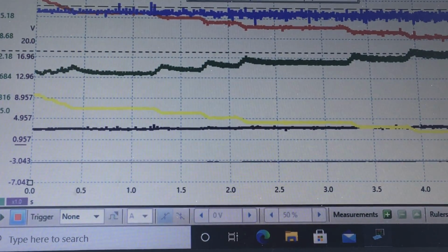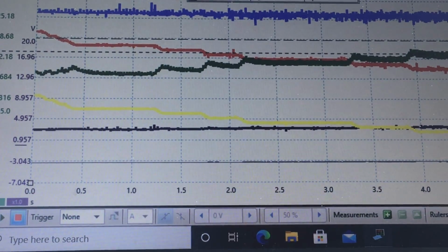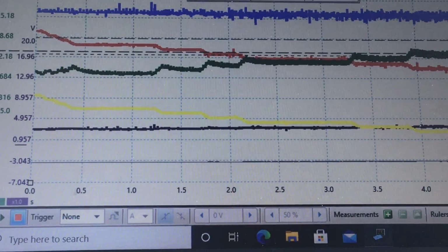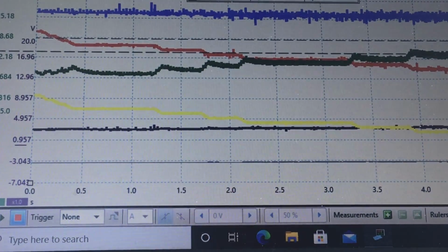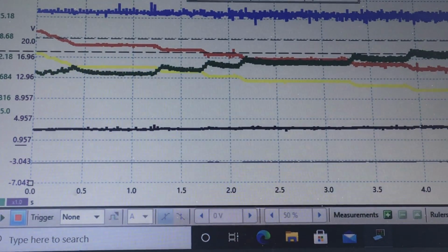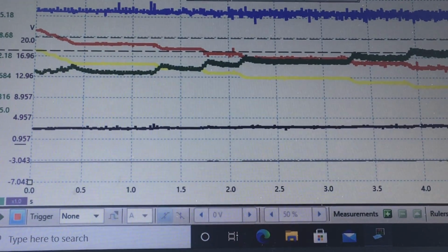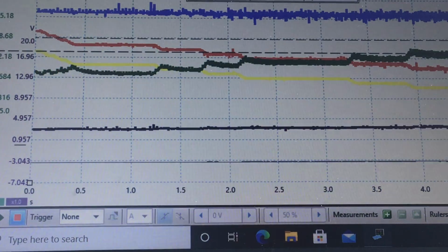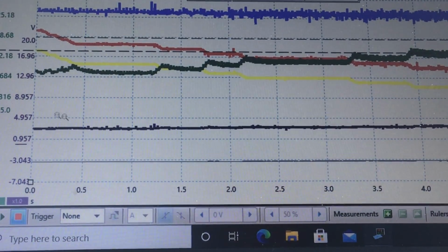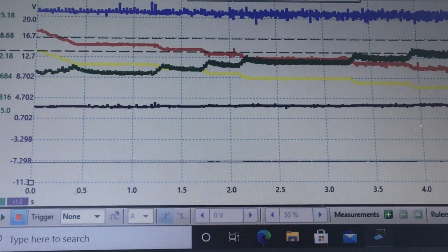Our voltage drop is actually decreasing, which makes sense. Kind of Ohm's law here. We look at red, and we look at our voltage drop getting less and less as our current gets more and more. There's definitely a parallel there. Our yellow circuit, which monitors the speed of the blower motor or monitors the voltage drop for that HVAC module, pretty much mirrors red. So you can look on your schematic. It's just monitoring what the voltage drop is doing. And our purple guy is at a certain voltage, let's see what that is.